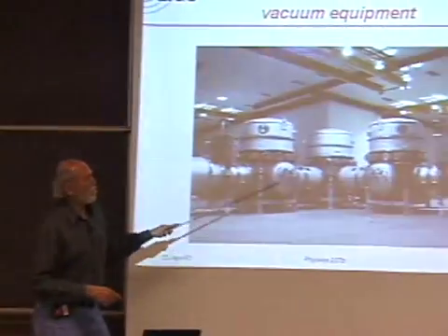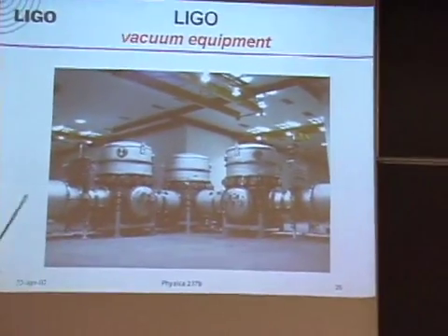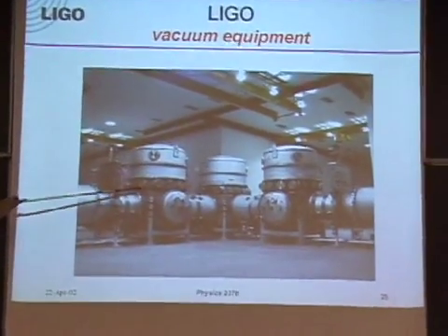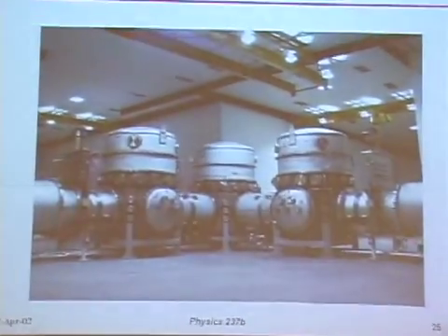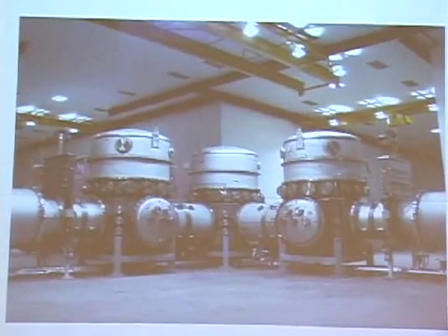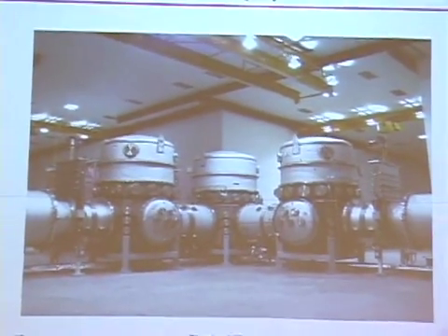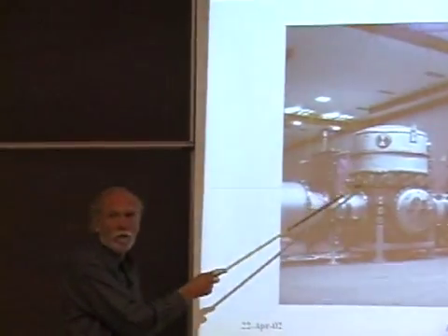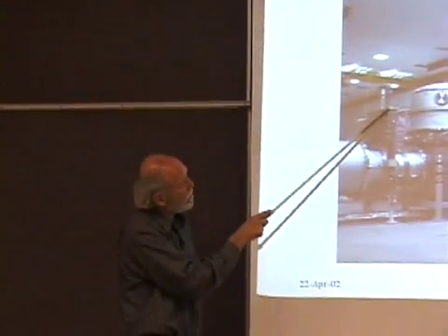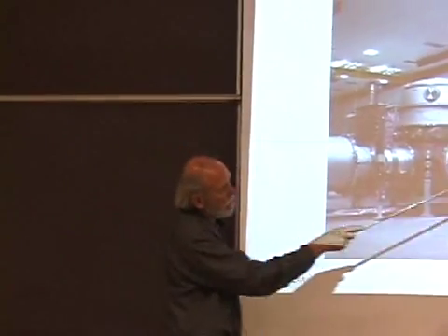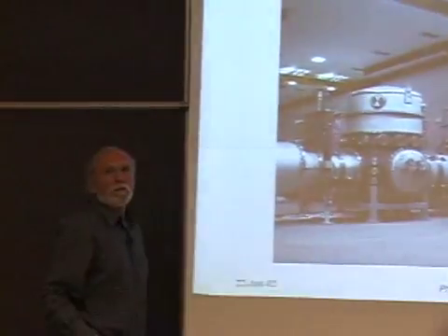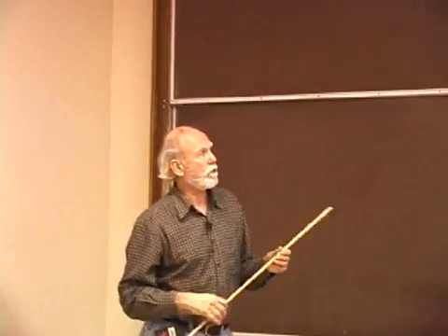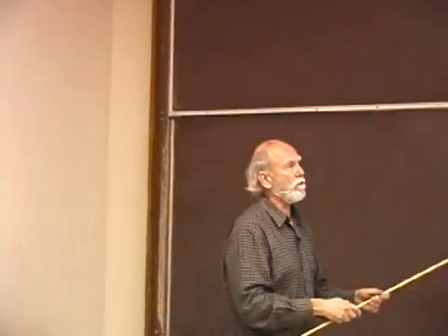These are the big vacuum chambers, and what to notice is they're about 15 feet high or so, and there's a lot of ports. That's because there's a lot of different axes and different side beams and alignment things and so forth that you want to have. They are under high vacuum also, but what's on the ends of each are this thing here. See the thing here and here? These are gate valves, larger than you can buy commercially. They're 4-foot gate valves, and they close off this long vacuum.